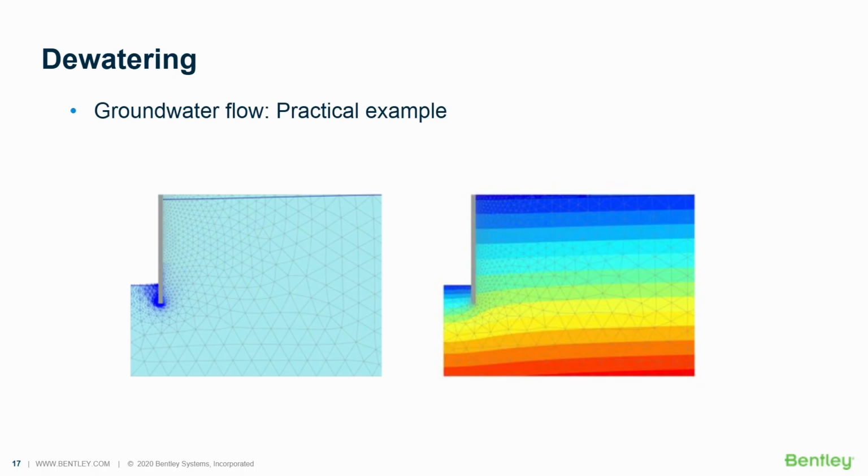And because we are using Terzaghi as a main assumption for most calculations, the total stress is always the sum of the effective stress and the pore water pressure. Even if you don't change the load, changing the pore water pressure will bring considerable change to the effective stress. And this is what most of the time will cause the convergence issue. They are quite difficult to identify sometimes, and this is what I'm intending to help you with in the rest of this presentation.